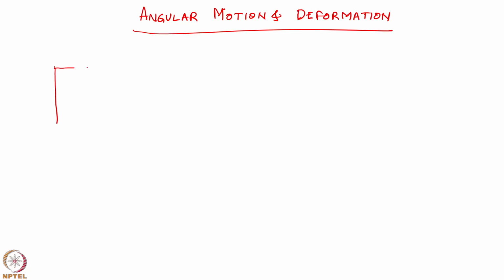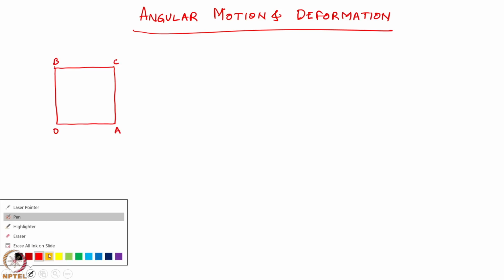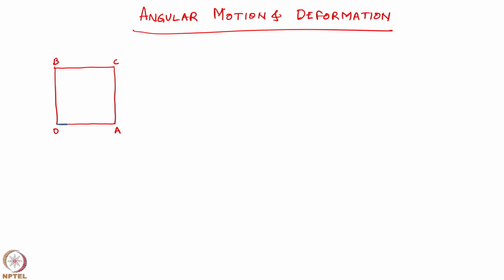So you have a square, that is a fluid particle, O, A, B, C. Now you have the velocity here, U, V. The velocity V changes in the x direction over length delta x, so here it will be V plus the gradient of V in the x direction, dou V by dou x into delta x.